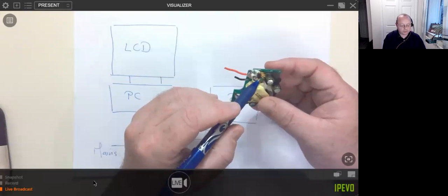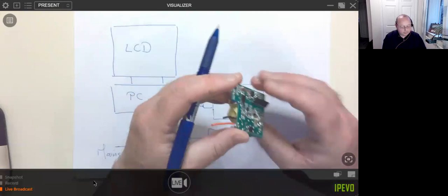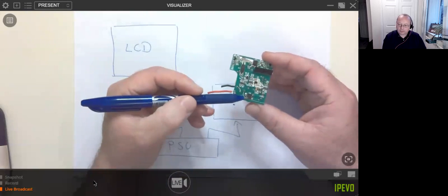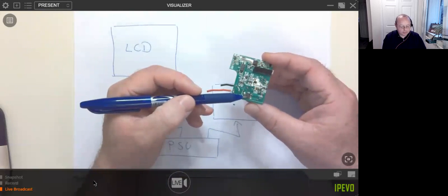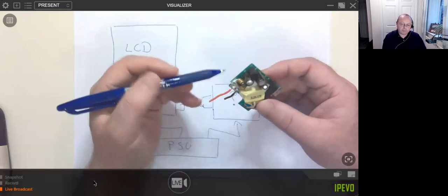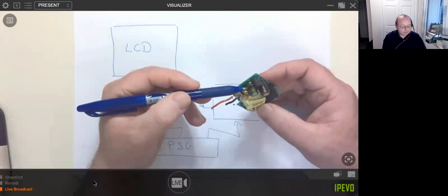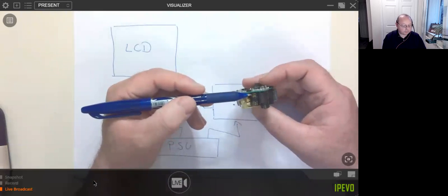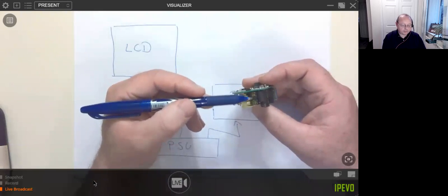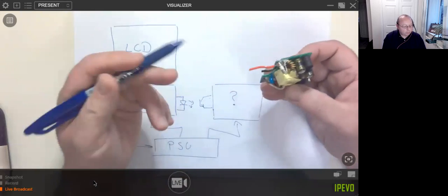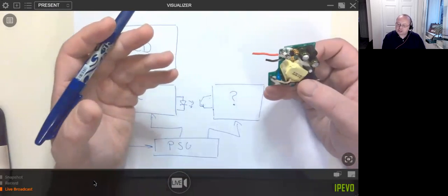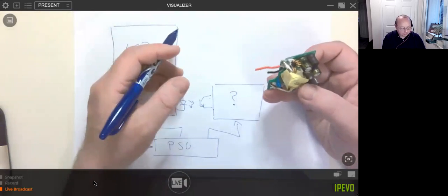So that's about the only good thing about it. Then it goes through this black block here, which is the full bridge rectifier. And then we've got a 400 volt capacitor. I know it's 400 because it says on it 400 volts, so it's quite easy to work that one out. Where is the protection in this for 2 or 500?